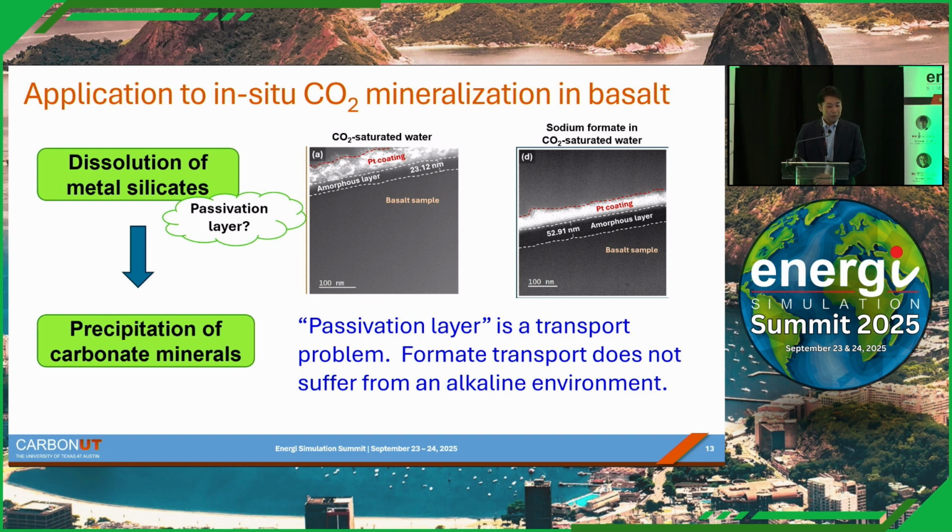One note here is that the term passivation layer is a little bit confusing because the surface is not protected by anything. Rather, it's a transport problem. And as I said, the formate transport is not hindered by this amorphous layer because it doesn't feel the pH gradient, unlike conventional proton-induced dissolution.